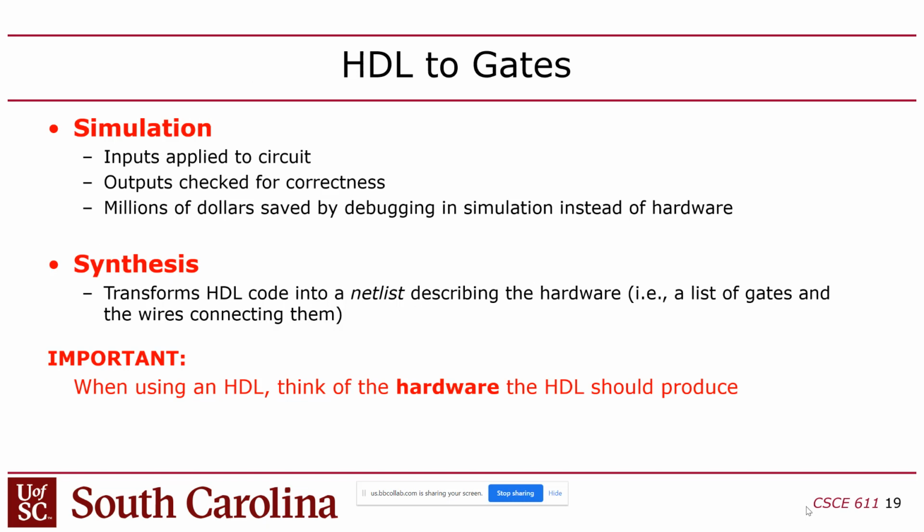That's all. And the other neat thing about those two is that I can take a VHDL module and a Verilog module and literally just plug them together and simulate them together, or synthesize them together, because the synthesizers and the simulators don't care which one you use. So they're interoperable. Okay, so I already mentioned the difference between simulation and synthesis.